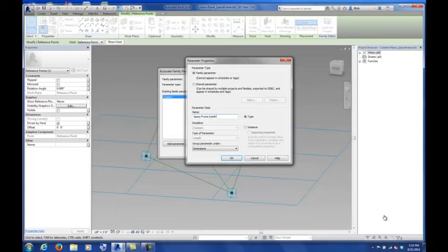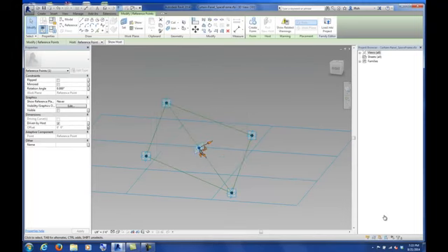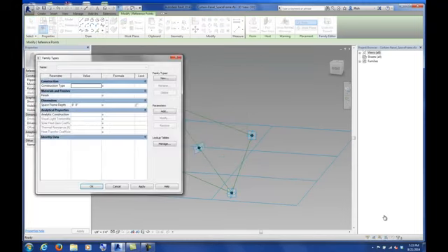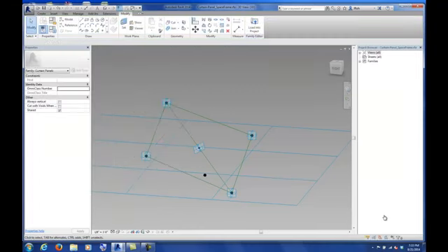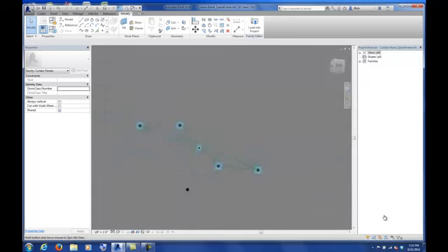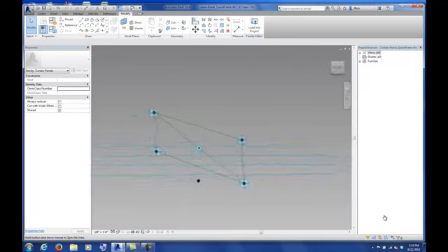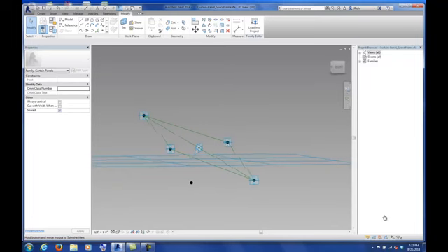And I'm just going to click OK and then OK. And if I go back to family types, that space frame depth, I'm just going to give it a number. Let's say for now 4 feet. Let's do 5 feet. That should move that point offset from where we just placed it.